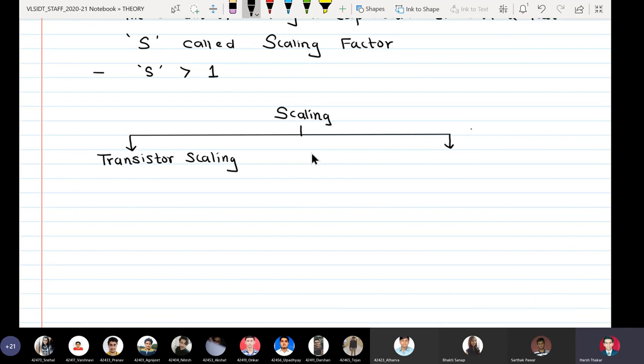In unit number 2, we defined what interconnects are. Interconnects are nothing but connecting mediums, and anything can be called an interconnect. The passivation layer, N plus, P plus, wires, vias, everything can be called an interconnect. There are two aspects of a silicon wafer: one is the transistors or active devices, and second are the elements which connect the transistors together. Interconnect forms more than 70% of the area on a silicon wafer, and only the remaining 30% is taken by the transistors.